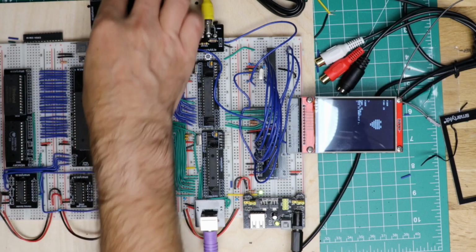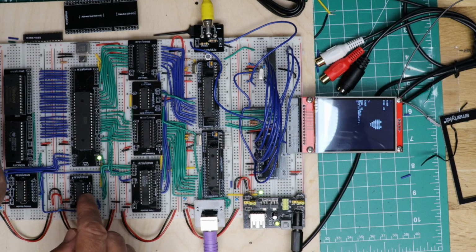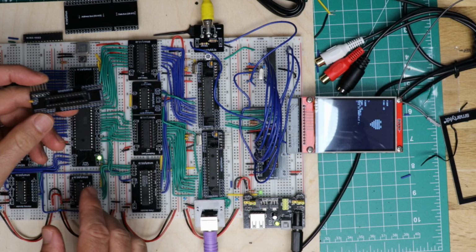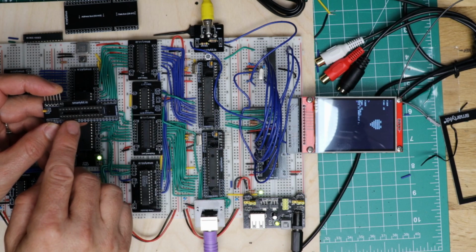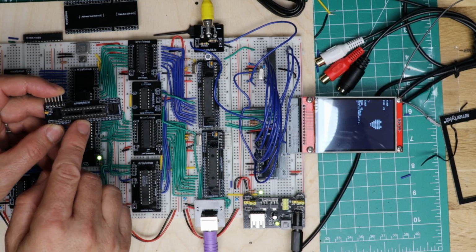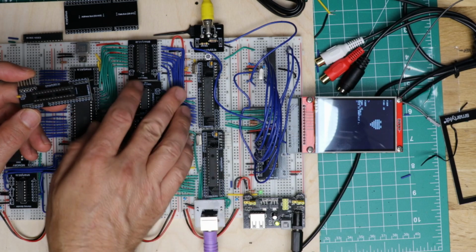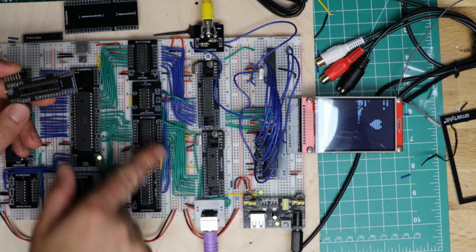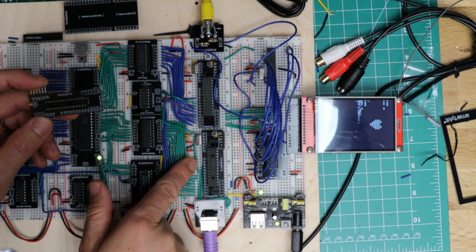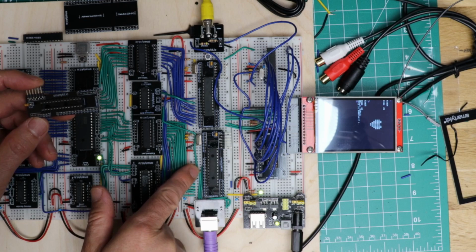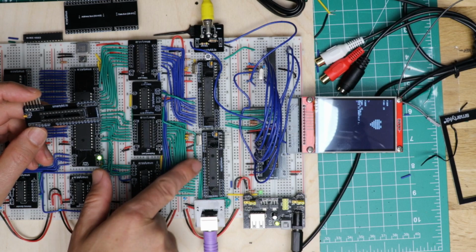Because of the issue I had with this, I started doing continuity testing on all the boards just to check when something wasn't going right. And it turns out that all three of these boards have the same issue. All D1 through D3 are shorted out. It doesn't pose a problem on these boards because those ports, if you look here, are not used, and so you don't notice it. Although, interestingly enough, the clock line on this one is used, but evidently there's enough going out there.